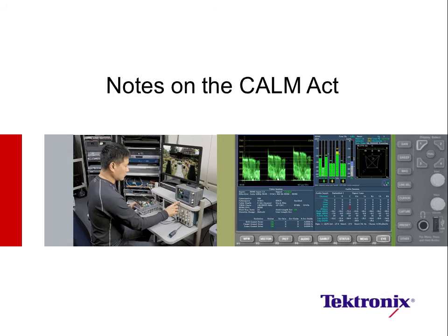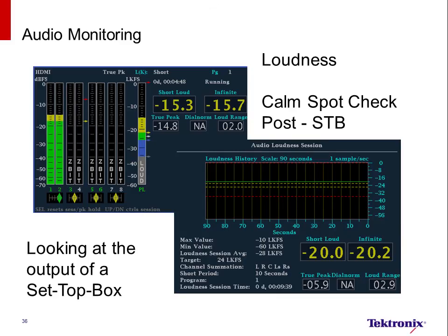Now we're going to take a look at set-top boxes, the COM Act, and what happens with set-top boxes when they are hooked up to TV sets and sending either the Dolby AC3 to the set-top box or sending linear PCM out from the set-top box to the receiver. We can do audio monitoring also with the WFM 5250. We can look at the audio output of a set-top box being presented to a TV set.